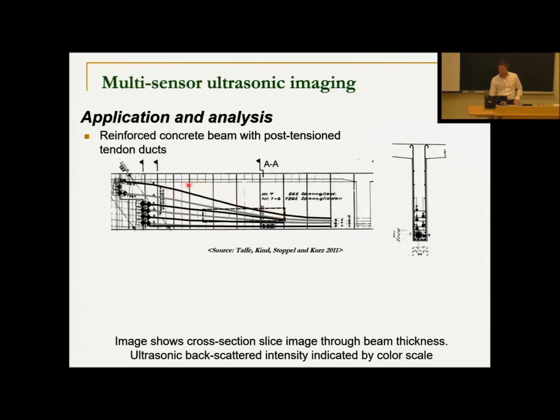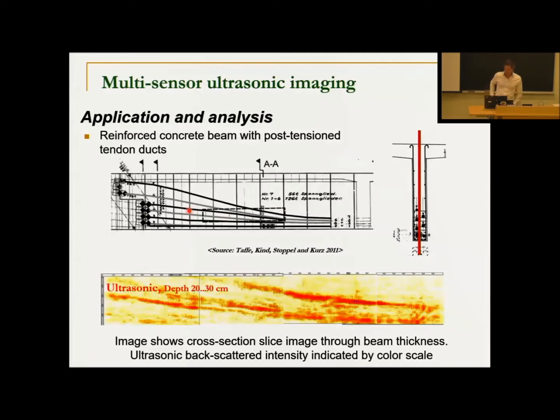They want to find the position of these internal ducts. Now these internal ducts are reflectors, so we should be able to see them, right? So what we can do in this case is do other kinds of complicated imaging. Even though we collect data all along this face, we take all of this complicated data and then reconstruct the reflectors along a single slice of the cross-section.